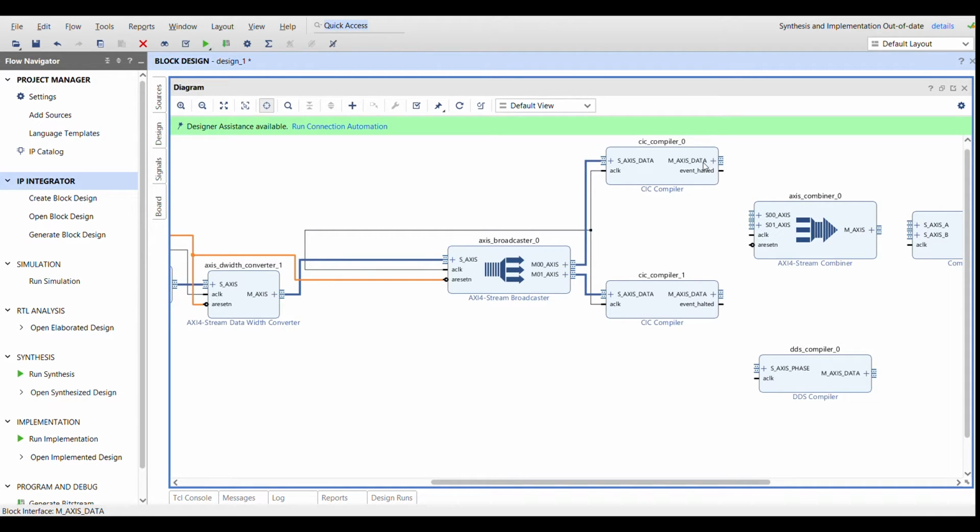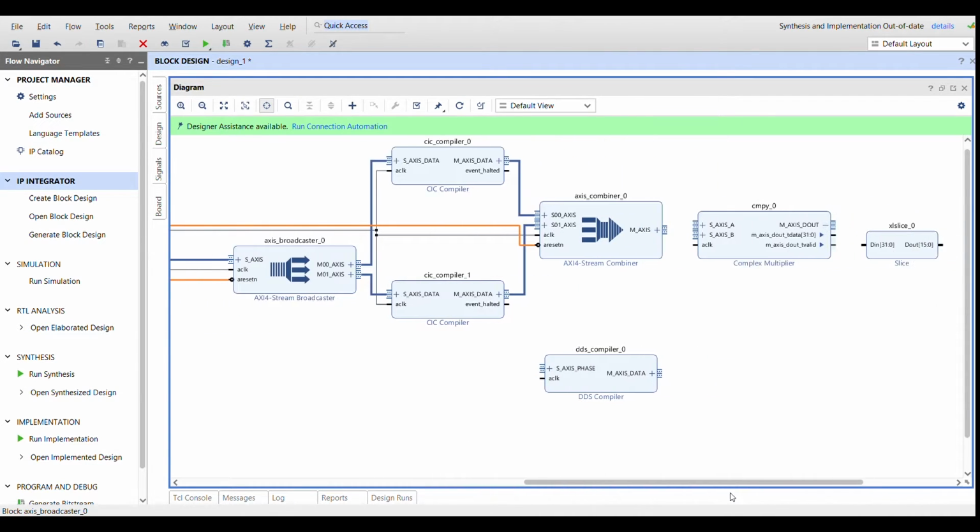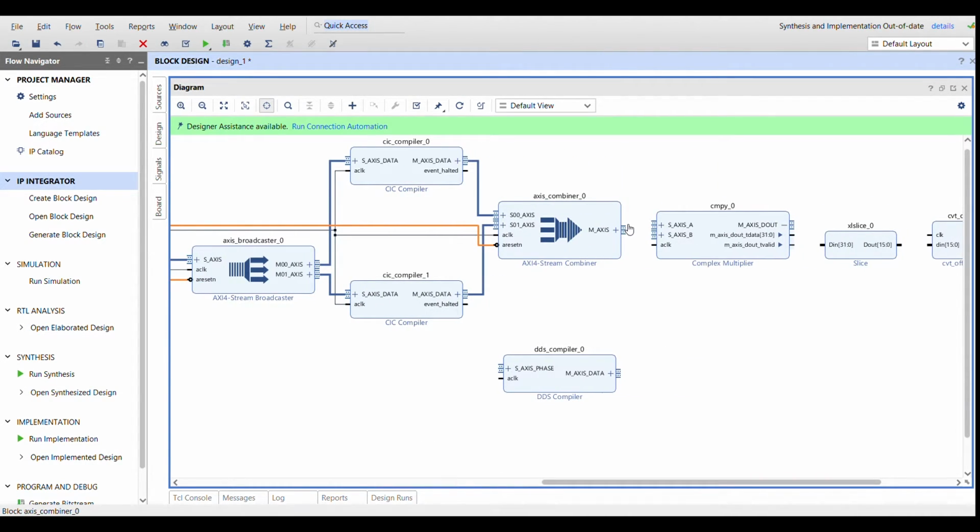So we start off with a separate I stream and a Q stream. An AXI stream combiner will then give me a single stream, twice the width, but it's a single IQ quadrature stream. Again, hover, drag, it doesn't matter whether it's source to destination or the other way. That's got everything connected up. The output now here is the modulated signal. That is ready to modulate the DDS.